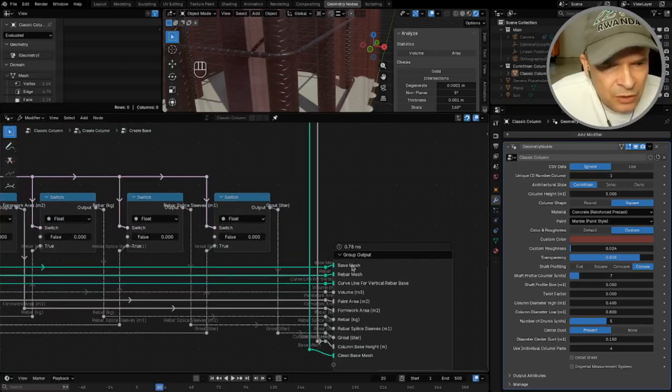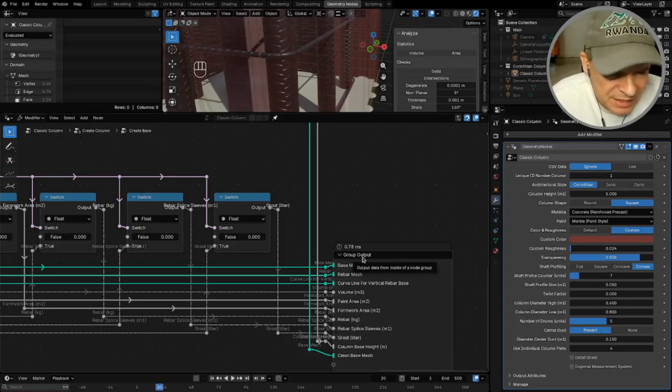You can see here that we don't put it together, so we don't join the mesh, because I also want to do separate things with the separate types of mesh later. Especially when I have these 2D drawings, I want to separate the rebar mesh from the concrete mesh, or the material, because I want to show, in a different drawing, only the rebar.